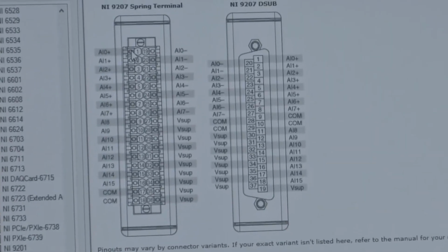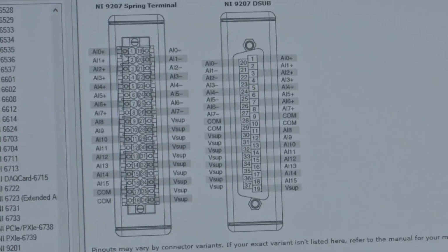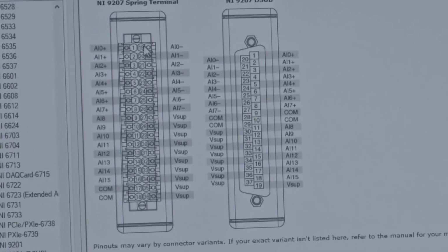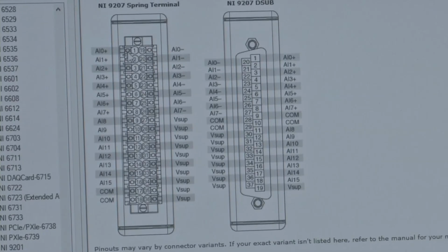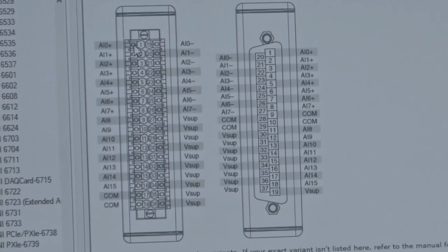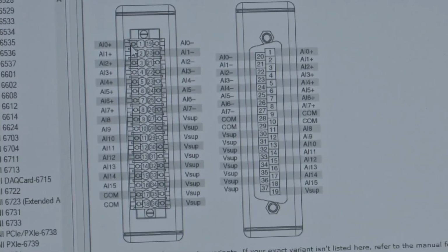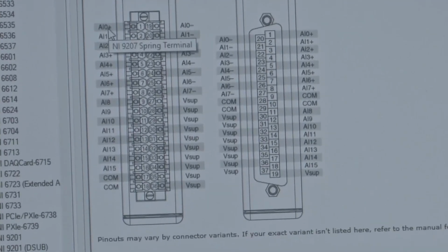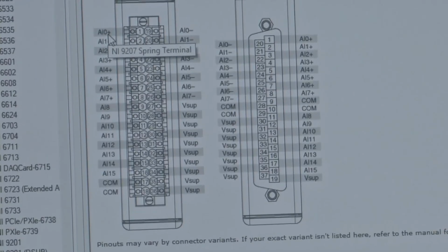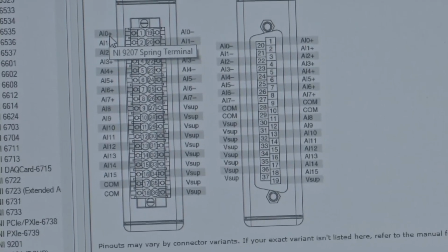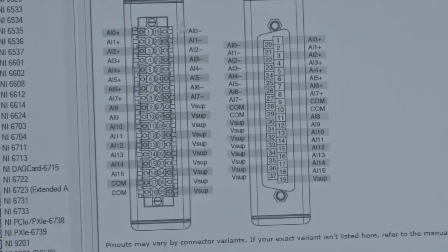The output from the temperature sensor will be connected at this point and at this point. This is ground and this is the output voltage. Since it is connected to the acquisition pin, AI represents analog input channel 0, it records the data and displays it in a software.